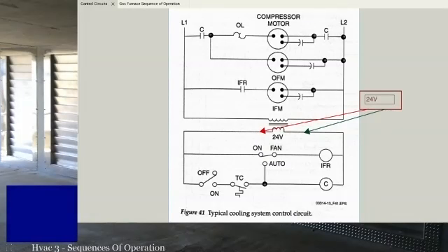So just watching those things operate as you're trying to troubleshoot something will usually get you through about half of the weird ones. So never forget those first few items. Line voltage is good, low voltage is good, power stays at rated voltage, low voltage power stays at rated voltage, and no external safeties are screwing with you.